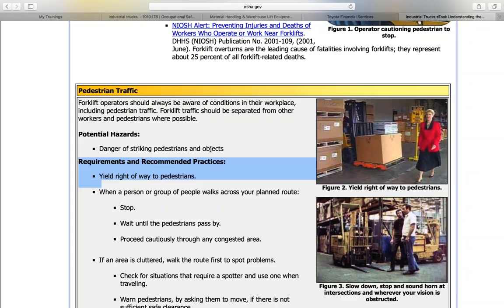Also, if we're traveling with a telescopic boom forklift, we want to make sure that the boom is fully retracted, right? So we want to try to pull that boom in all the way. Look at the SkyTrack again, and you'll see what we're talking about in the bottom left-hand picture. Pull it in as close as possible to the vehicle itself, and travel with it in that capacity. Okay. Also, it may be a regular fork truck. It may be a Type 4, a Type 5 fork truck that may push out. It may have what they call an outrigger, actually, on a forklift.